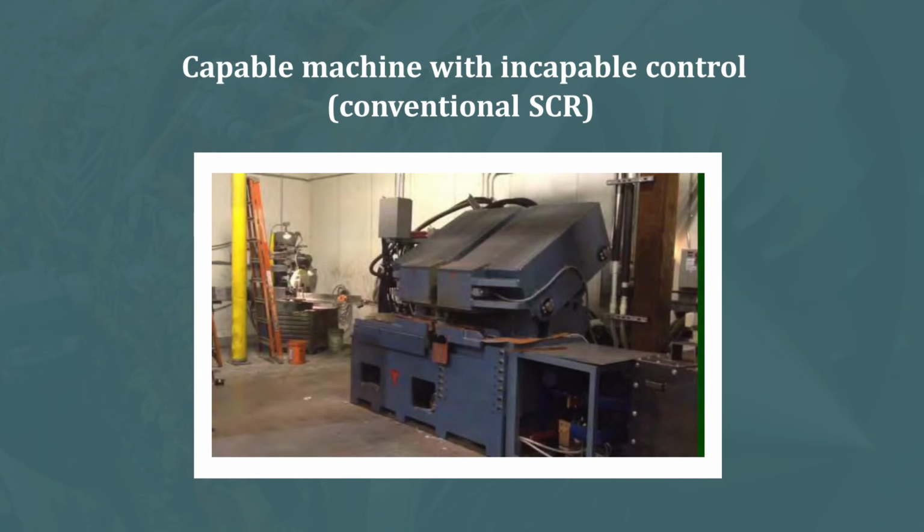You could see that there was just intermittent flashing on and off all the time. This operation is plagued with never having quite consistent flash. And then they wonder why they can't control a consistent upset process, even though they're monitoring.